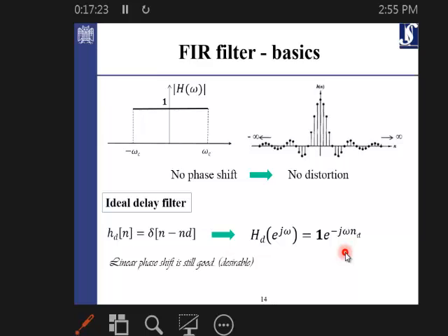It's because of distortion, because phase is not consistently moving. So if you have a linear phase shift, you will not notice anything. But when you have a non-linear phase shift, you need to have a consistency in the phase. If there is no consistency in the phase and it's changed non-linearly, then the effect of that phase changing in nonlinear form, which in spectral subtraction and Wiener filter you can understand just by listening, for example in the speech case, then you'll understand this phase shift. Phase is not consistent with the amplitude.